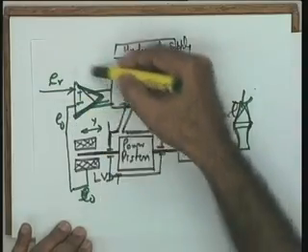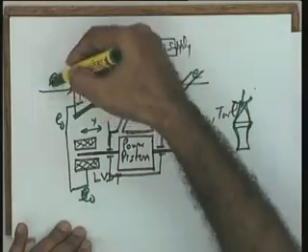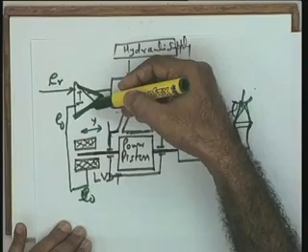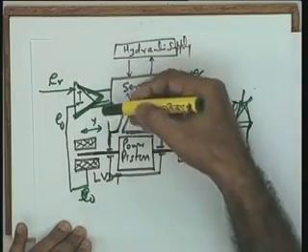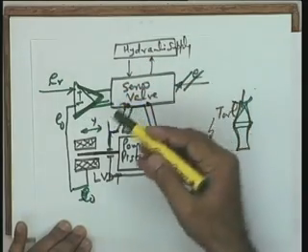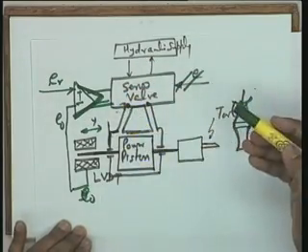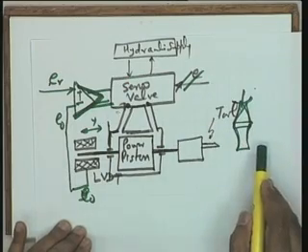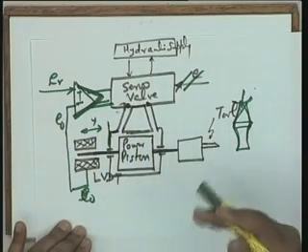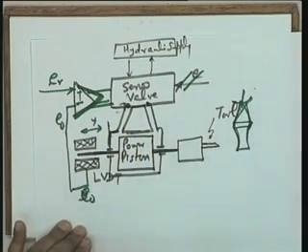With this hardware configuration available to you, your job as a control engineer will be to design a suitable control function which will act on the error signal and give suitable control on the manipulated variable, so that the output follows the command without any transients and with as good a static accuracy as possible.